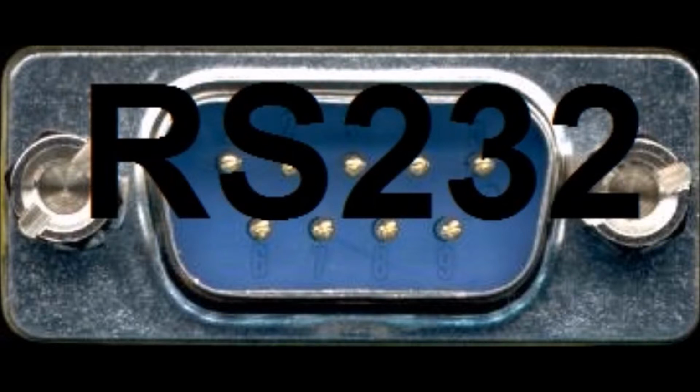RS232 data is bipolar. With today's technology, modern computer equipment ignores negative voltage level and accepts a zero voltage level as the off state. That being said, an on state may be achieved with lesser positive potential. This means circuits powered by 5 volts DC are capable of driving RS232 circuits directly. However, the overall range that the RS232 signal may be transmitted or received may be noticeably reduced.